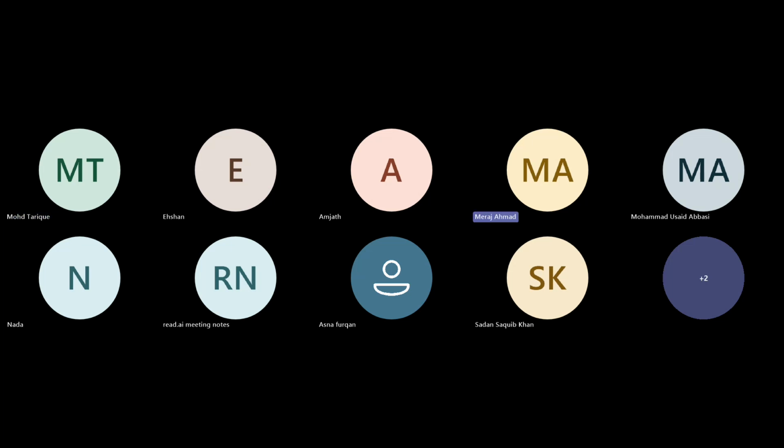Yes, exactly. From here, we have post synthesis functional and timing simulation. Then we have post implementation on FPGA fabric, with routing and everything considered in this type of simulation. So the same test bench can be used for behavioral simulation, post synthesis, and post implementation.